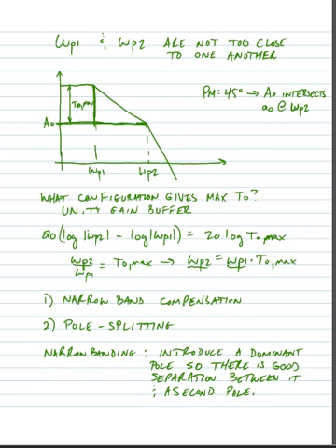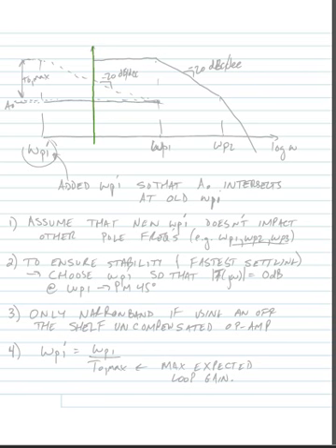If we draw this graphically, you can imagine that we have a Bode plot for our original operational amplifier, and it has some frequency response where we have some original pole and some second pole. So say we have omega P1 here and omega P2 here, and we determine that omega P1 and omega P2 are too close to one another.